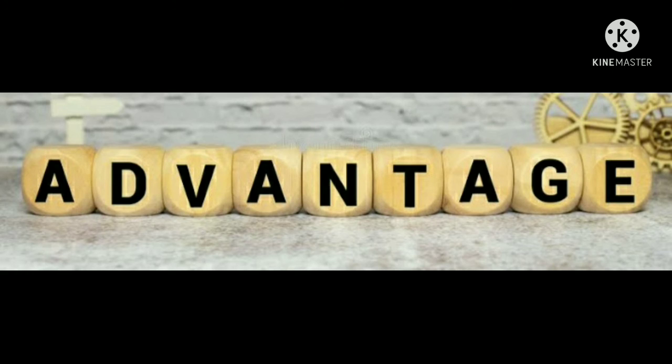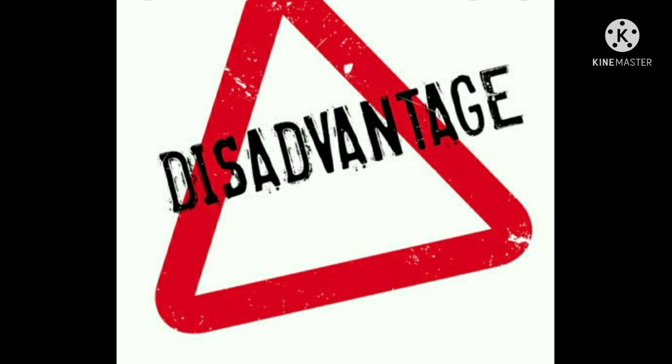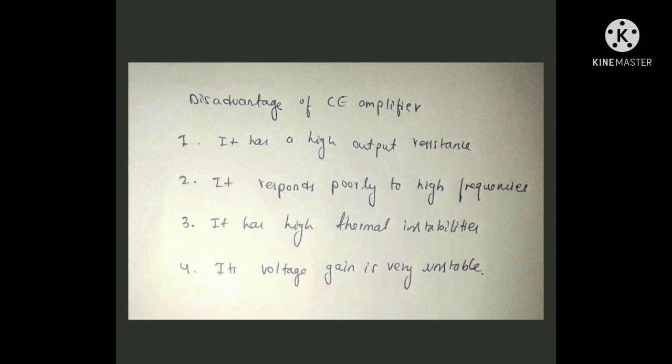Advantages of CE amplifier: number 1, a common emitter amplifier is inverting and has low input impedance. Number 2, high output impedance. Number 3, high voltage gain. Number 4, high current gain. Disadvantages of CE amplifier: number 1, it has a high output resistance. Number 2, it responds poorly to high frequencies. Number 3, it has high thermal instabilities. Number 4, its voltage gain is very unstable.